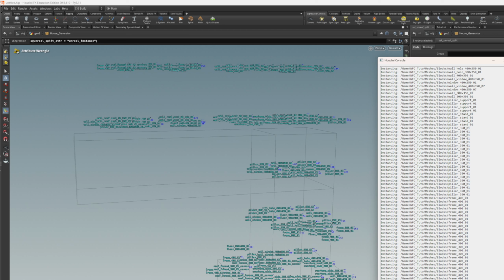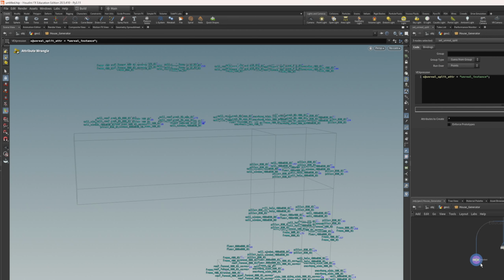And this is kind of what proved it, was that I debugged that it was checking to instance meshes in the content folder, and it was looking for them, and it was running the string, which confirmed that each one of these points should have been getting instanced from that content folder. But we could tell it didn't work because it not only didn't instance the meshes, but it didn't even create Houdini debug blocks in Unreal, which meant that the HDA just wouldn't have worked.